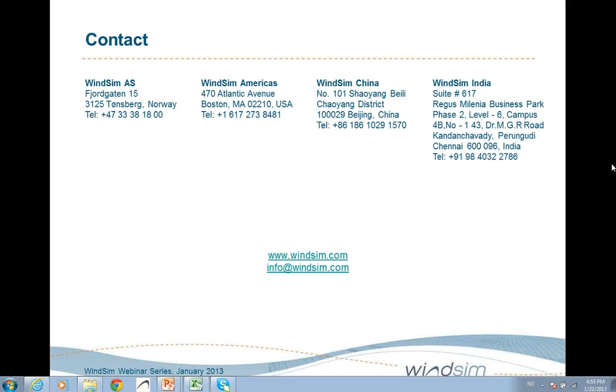The first question which came in was if WindSim is able to capture and to visualize recirculation. Yes, of course, WindSim is able to capture recirculation. This is what the CFD model is for, and you can also easily visualize this. We have in the objects module a 3D graphical tool where you can easily visualize, for example, the wind direction and the wind speed, so there you can easily see the recirculations.